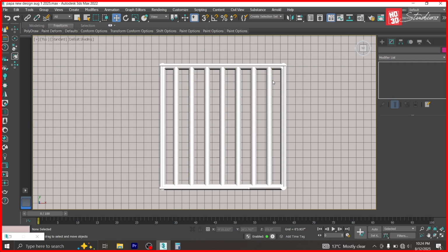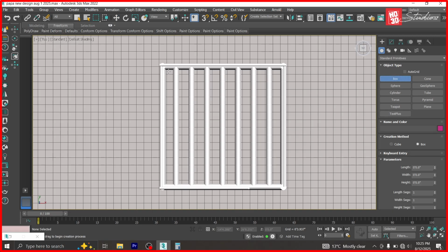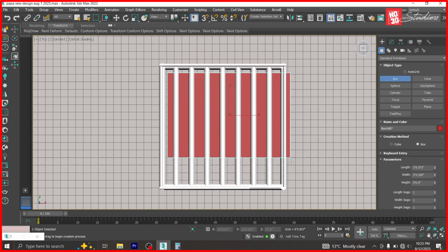It's going to have a hard time doing it, but with time, because of the sun and the rain hitting the plastic tank, it will eventually take a slightly deformed shape at the bottom. This eventually causes leaks. So what most people do is they install a plate here.